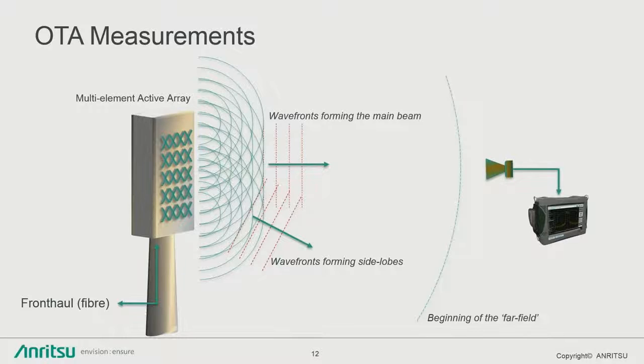So from the far field, if I say, okay, I'm pointing right into that center beam, the beam I'm making a measurement on, and I know I have X gain and X loss, then the instrument says, okay, based on this distance and gain and loss, that radio is putting out X number of dB or watts, right? Then you can look at the radio specification and say the radio puts out 250 watts. When I'm out there at the field, I'm getting 242 watts. Okay, it's within spec.